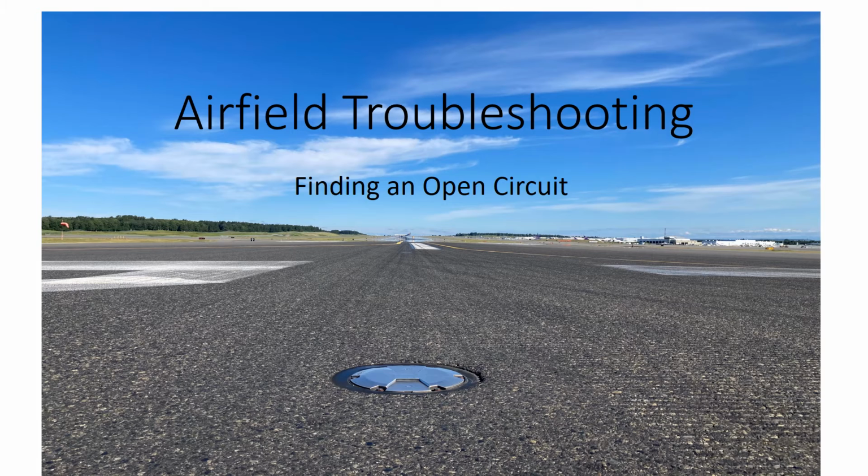An open circuit in an airfield lighting circuit is a situation where a wire in the field has been parted or a connector has been pulled apart or burned open and there's no more flow of electricity through the circuit. This will result in the regulator shutting itself down and the circuit will be unusable until it's repaired. So because of this, open circuits are usually considered an emergency repair, especially if it's a circuit like a runway where you will not be able to use that runway until it's fixed.